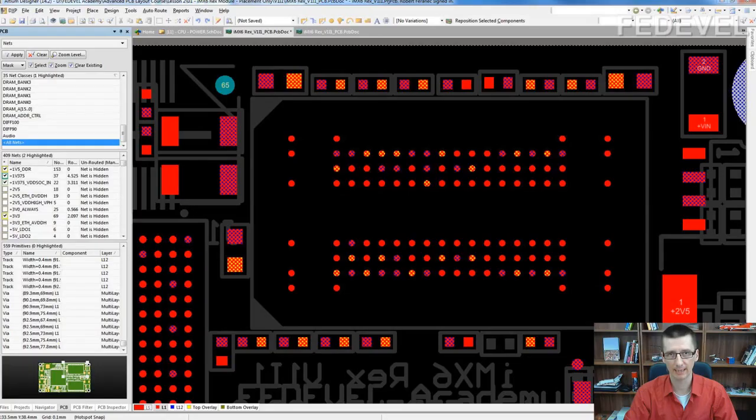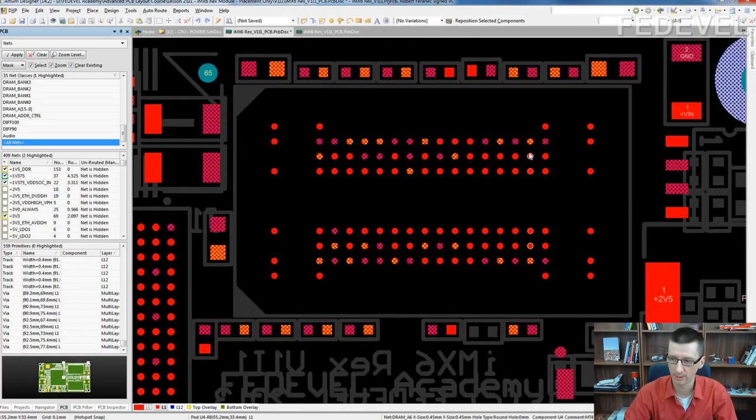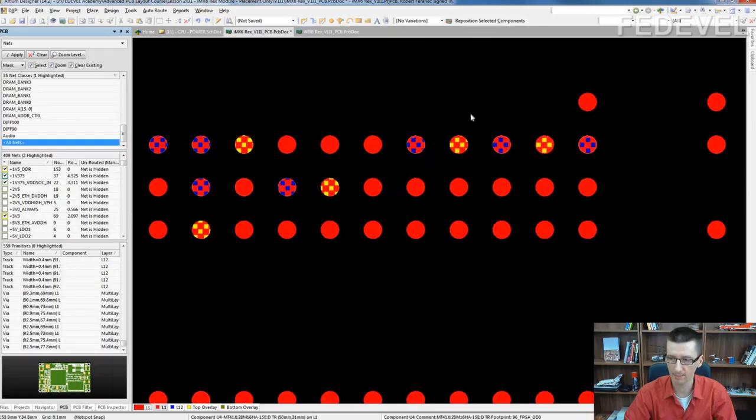Memory chips are designed the way that when you place one memory chip on top layer and one memory chip on bottom layer, the power pins can share the same power vias. I'll show you. Here is the top layer and here are some power pins. See?